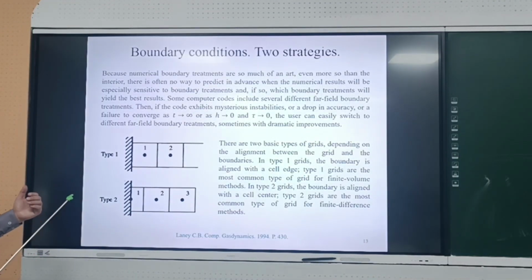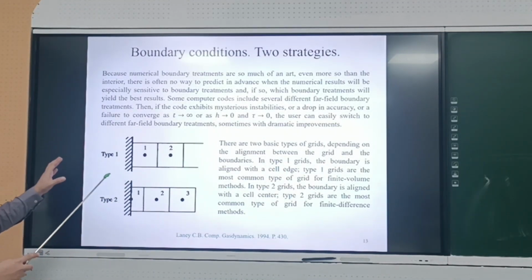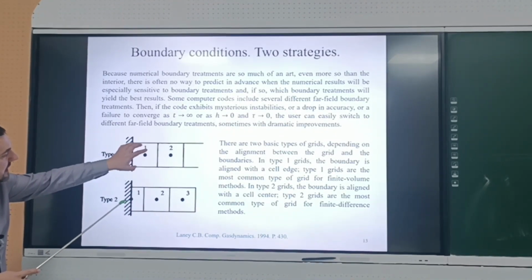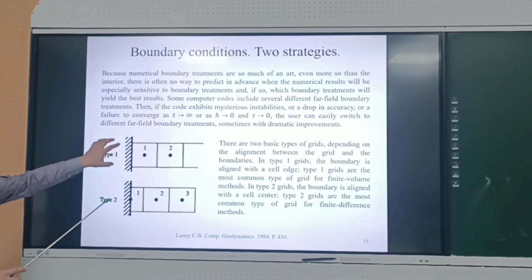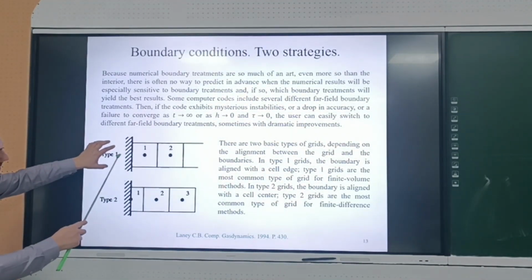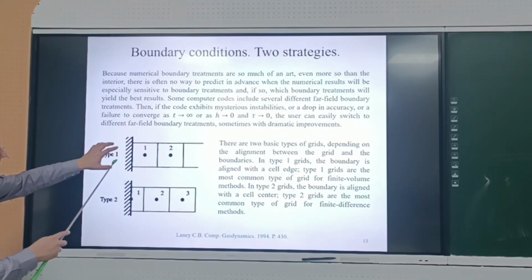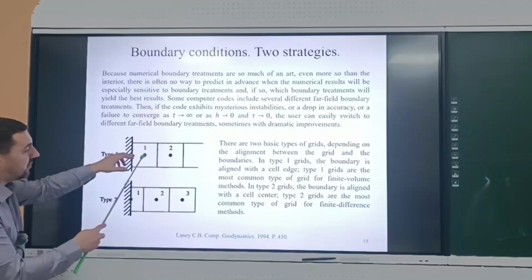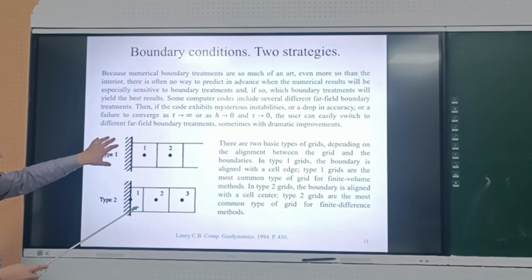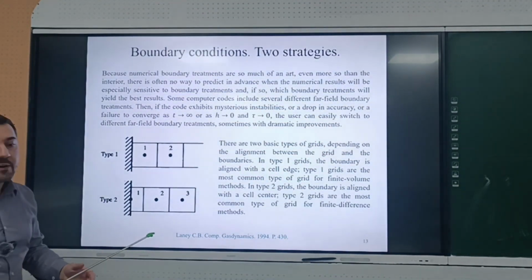There is another choice, where we want to keep the numerical method just the same. On this way, we need to compute this computational cell. It means that we should introduce a so-called ghost cell here, define somehow the parameters here, and then compute the numerical flux through this physical boundary in the same manner as we would do it for this boundary, and so on. So we introduce the ghost cell, define parameters in this cell, and use our general finite volume method.